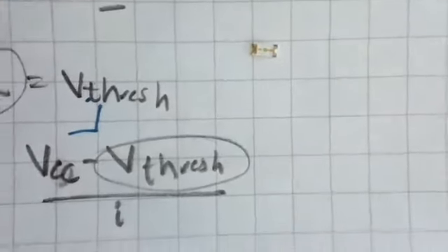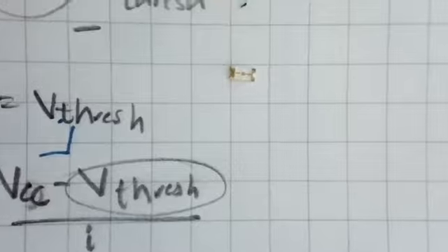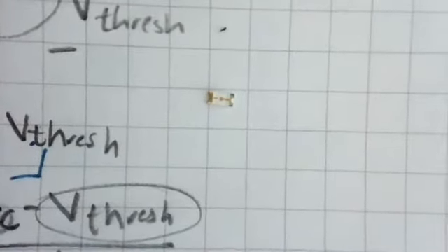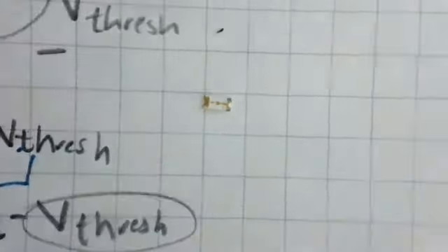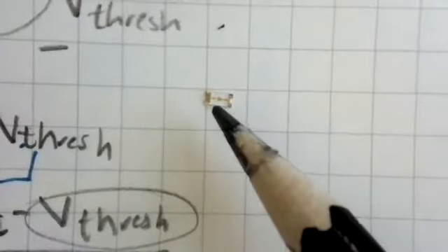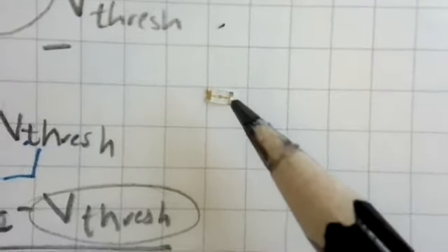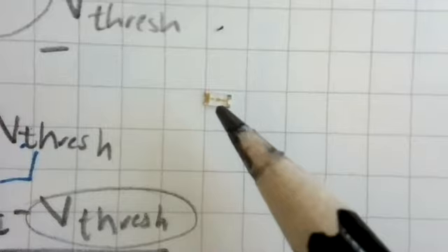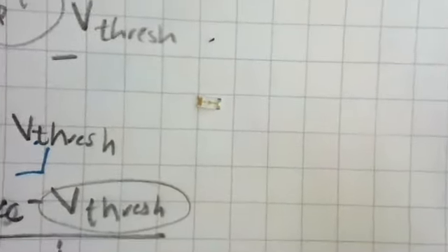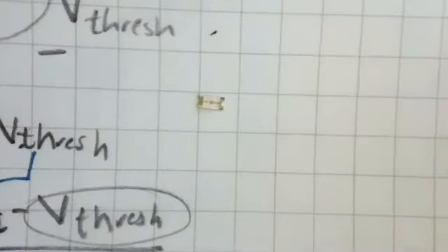So with this USB magnifying glass, you can see the two traces that are leading to the actual silicon that is the LED in this case. So the silicon is right there in the middle, and there's a ground trace it's leading to that's underneath it, and then coming off of this side, there's a little wire bond that we can't see at this magnification.